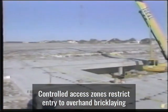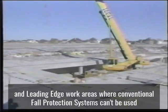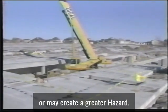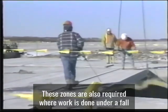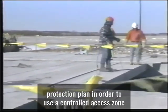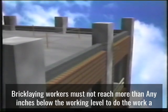Controlled access zones restrict entry to overhand bricklaying and leading edge work areas where conventional fall protection systems can't be used or may create a greater hazard. These zones are also required where work is done under a fall protection plan. In order to use a controlled access zone for overhand bricklaying, workers must not reach more than 10 inches below the working level to do the work.